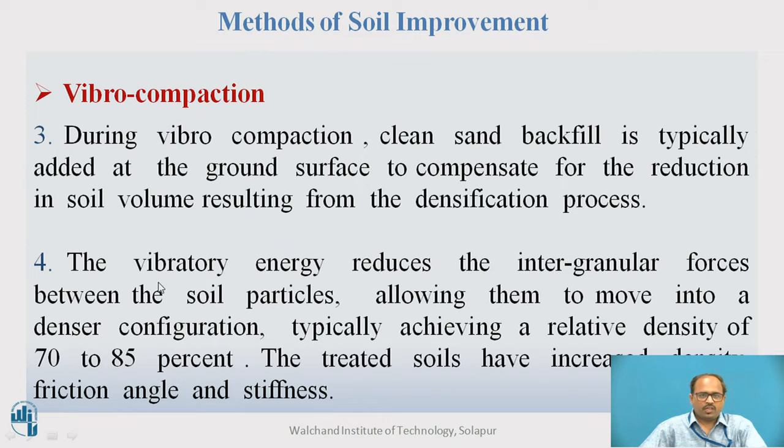The vibratory energy reduces the intergranular forces between the soil particles, allowing them to move into a denser configuration. If it reduces the intergranular forces between the soil particles, it moves into a denser configuration.